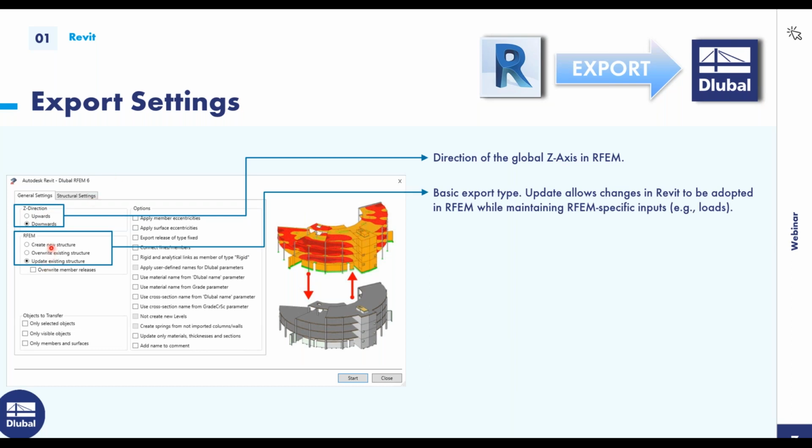The first option here is to create a new structure. What this will do is create a whole new blank file in RFEM. Then you can also choose to overwrite an existing structure, and this will completely delete the structure in RFEM and overwrite it with the structure from Revit. And lastly, we have update existing structure, and this will just update the items or the objects that you've changed